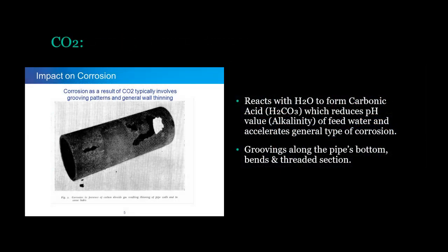CO2 reacts with H2O to form carbonic acid, H2CO3, which reduces the pH value, alkalinity, of feed water and accelerates general type of corrosion. Groovings occur along the pipe's bottom, bends and threaded sections.